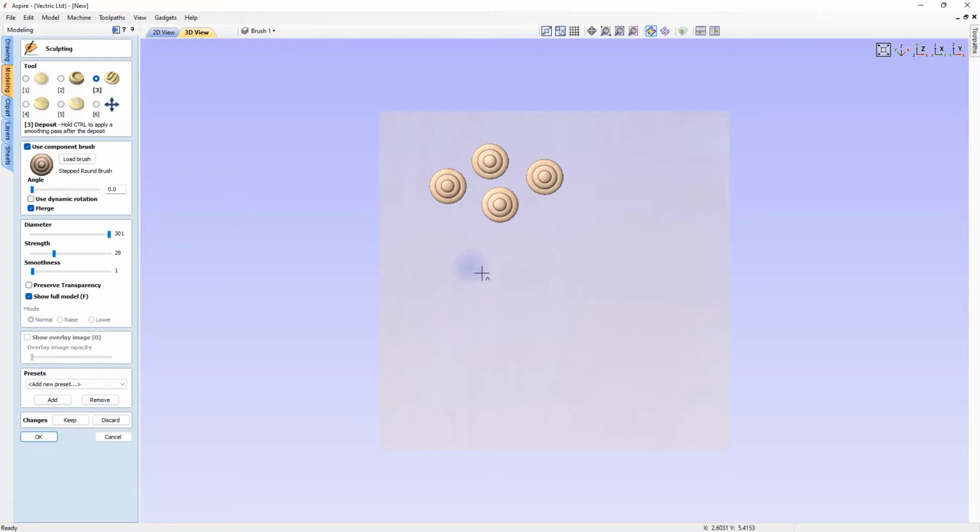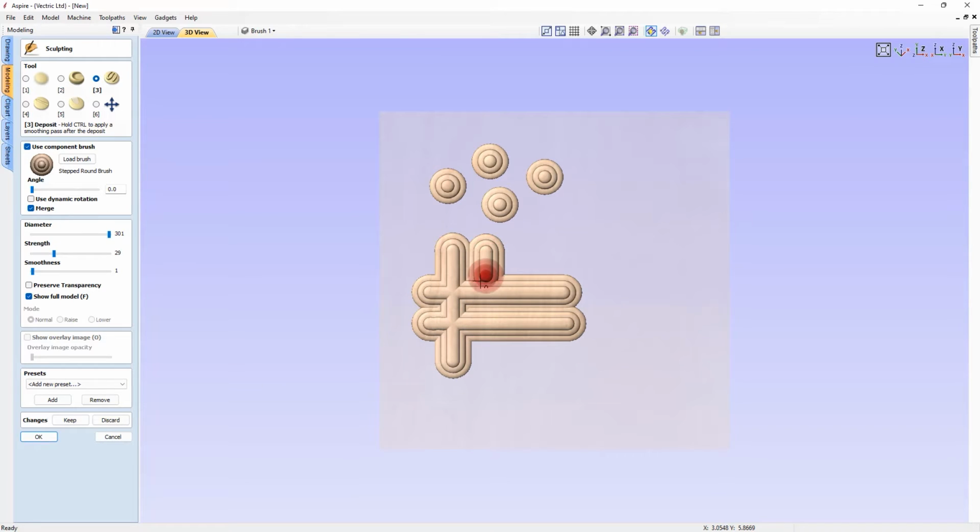Okay, so with our brush ready here, all we do is press H and that will keep us constrained horizontally, like so. Now we can do that again over here. To do the same but vertically, we simply hold down the V key on our keyboard, and then as we move our mouse down, you can see we're getting nice straight lines there.